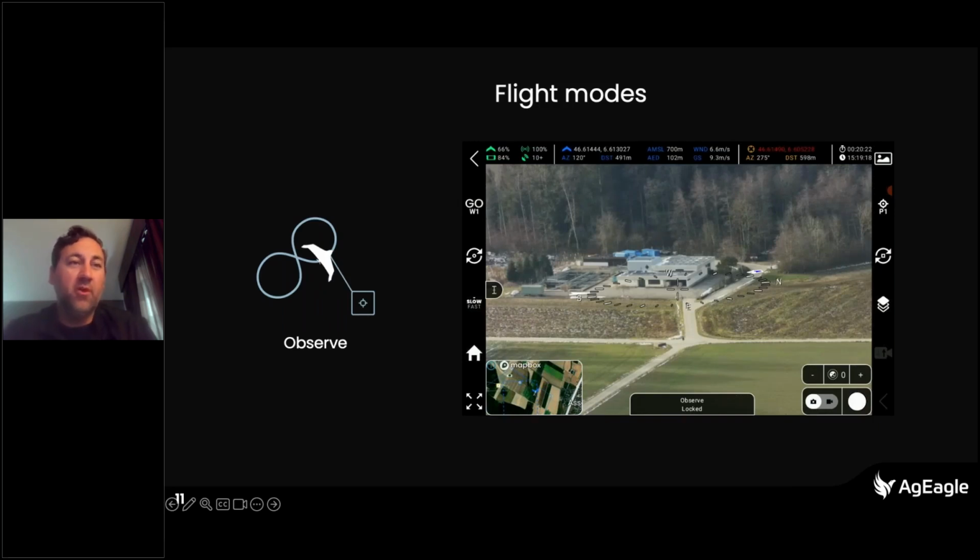But moving on to observe mode. Observe mode is going to let us discover things and then automatically tell the aircraft that I want to look at this continuously. And the aircraft is going to determine the best flight plan around that object or whatever you define on the geographical area to be able to continue to do persistent surveillance of that area. Once you're done there, you've collected your potential intelligence, right? You can then transition back to your flight plan mode. Or if something in that observed area continues to leave, that might be when I would transition to scout mode.